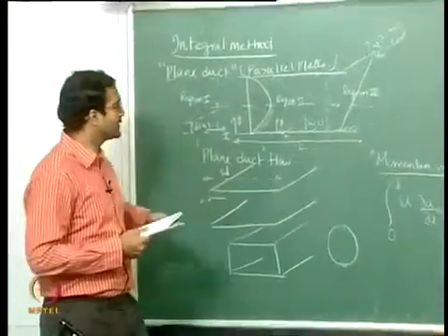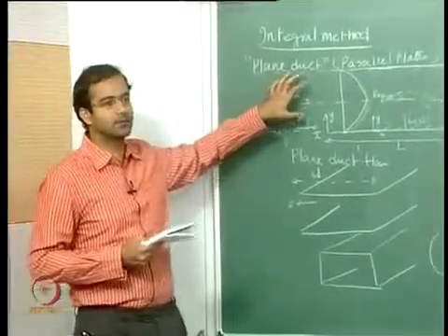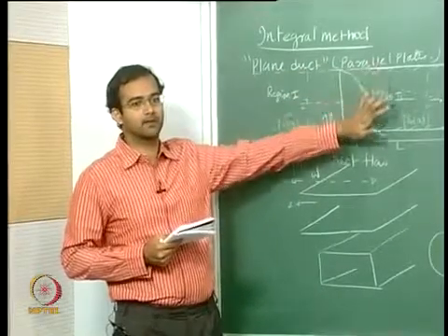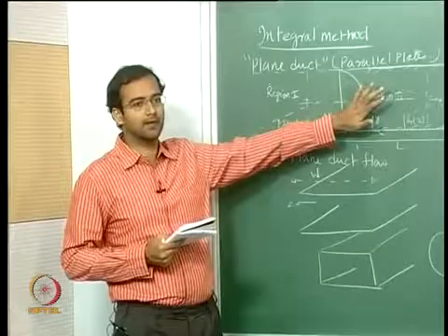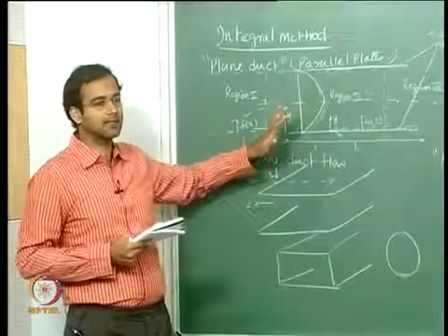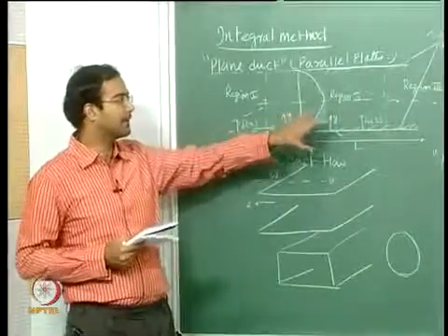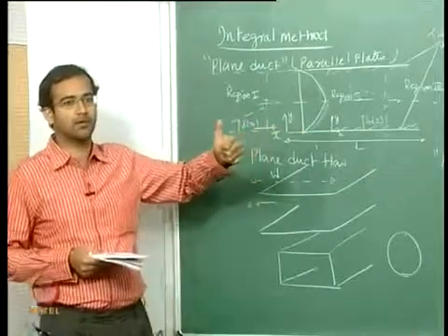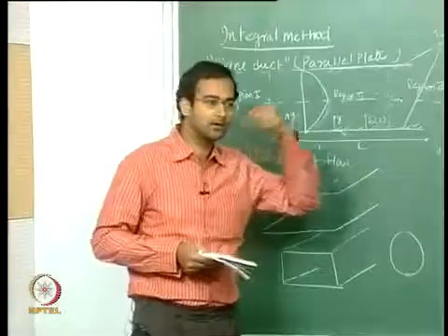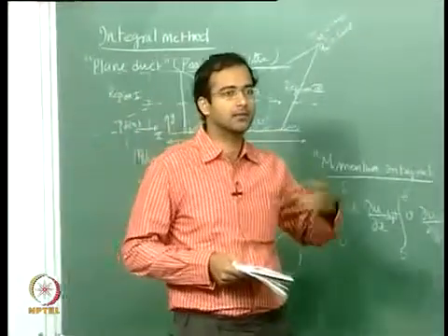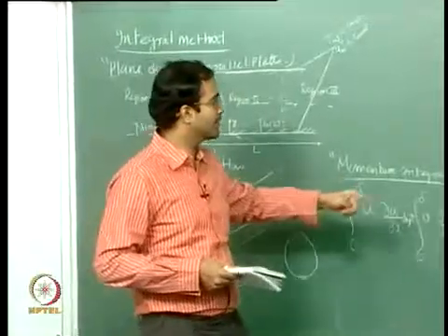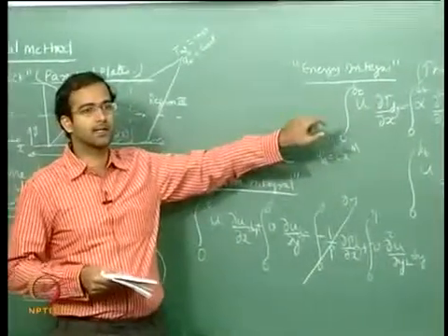So that is typically the plane duct. When you are looking at two dimensional flow in a channel, or between parallel plates, the energy integral is mostly valid for the thermal entry length problem, where you already know the velocity profile, but you do not want to go through the rigorous analytical solution for getting the temperature profile. There we can use the energy integral.